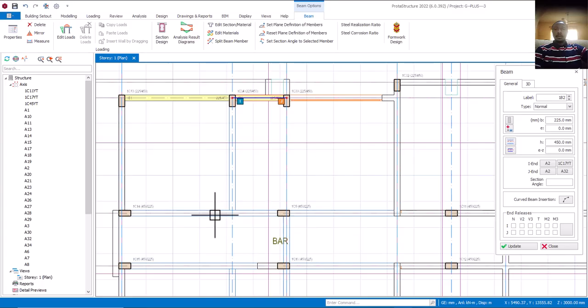Perfect. So this one now, I don't need it to be all through. So click on it, right click and click on stretch. I want to stretch it from here. I don't need it all through, I just need it somewhere here, and fix this around maybe here. Okay, that's okay. And also come to this other side again. This one, correct. And also stretch it. Stretch from this point, back to somewhere here. Okay, so I now have my horizontal and vertical axis.